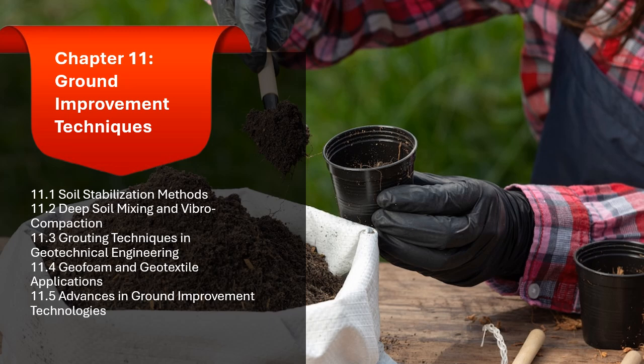Grouting is often a more cost-effective solution than other methods of ground improvement, especially for large areas or sites with complex soil conditions. Minimal disruption. Grouting is typically a non-invasive method that causes minimal disruption to the surface or surrounding structures, making it ideal for urban construction or sensitive environments.